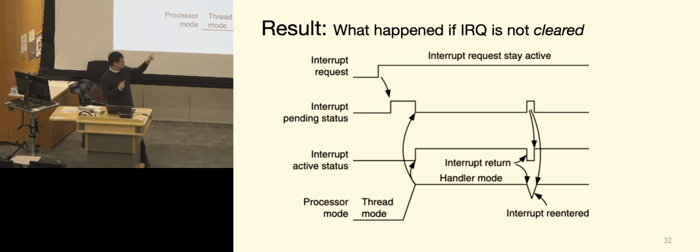It's caused by the processor checking to see that it's still active, so it got pulled up by the processor, and then that little bump got quickly shut down because that goes to the active state of that interrupt. So you just see a little bump here. Does that make sense to everyone? Okay, perfect. I think everyone's answers are correct, which is super nice.